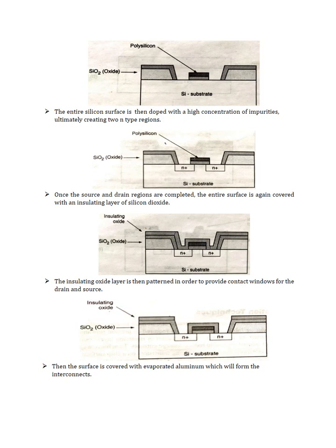Here you can see the extra oxide which is not desired has been removed from the sides of the gate, and N plus regions are doped, so it has become an N-type MOSFET. An N-type enhancement type MOSFET has been fabricated.